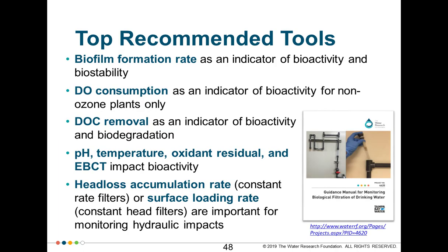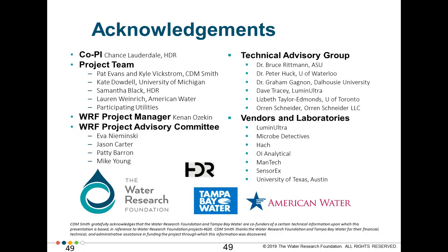And again, the top recommended tools that we included in our guidance manual are biofilm formation rate, DO consumption, and DOC removal as their indicators of biological activity. pH, temperature, oxidant residual, and empty bed contact time are certainly important for impacting bioactivity, and for looking at filter hydraulics, the head loss accumulation rate or surface loading rate are good tools for evaluating that.